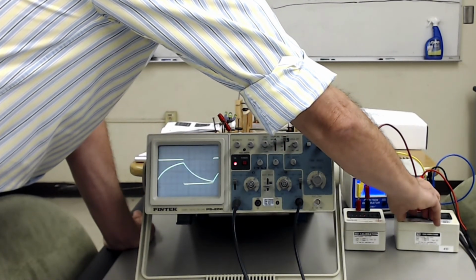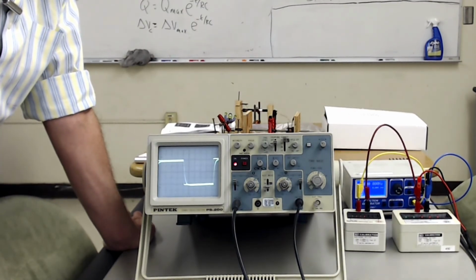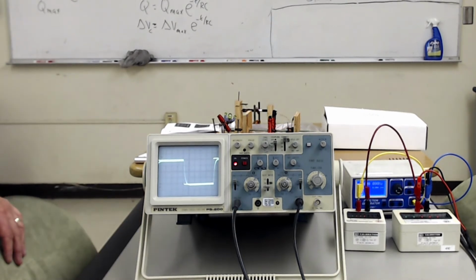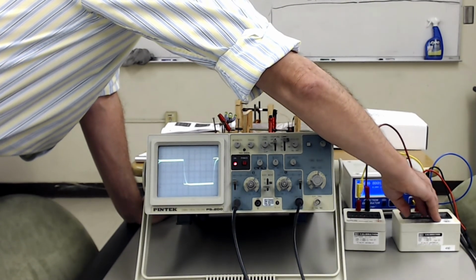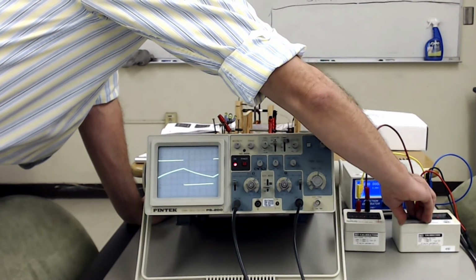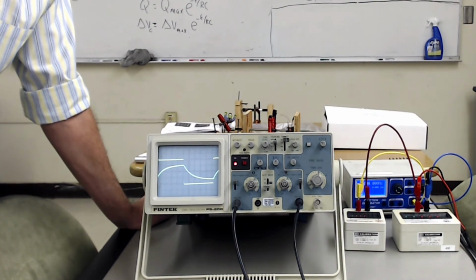Once I make it bigger, it won't charge up. So I changed the capacitor from 1 microfarad to 100 nanofarad. So I divided the capacitance by a factor of 10 and made my time constant shorter by a factor of 10. So now the capacitor has more time to charge up, and you can see it reaches the maximum voltage. And again, if I make the capacitance bigger, you see the capacitor doesn't get enough time to charge up.